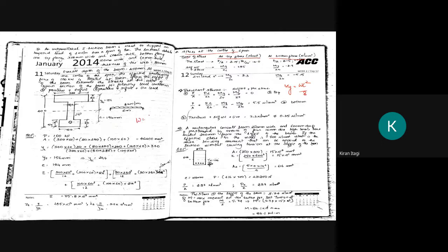W how we will calculate, dead load. Okay, you take all the components self weight, that is 0.3 by 0.6, 0.8 by 0.28 plus 0.6 by 0.1 multiplied by density. Okay, you will get weight. Okay, that weight you take it, that is Wg, and substitute in Mg, that is Wg L square upon 8. So you will get the moment due to dead load, that is how much it is there here.